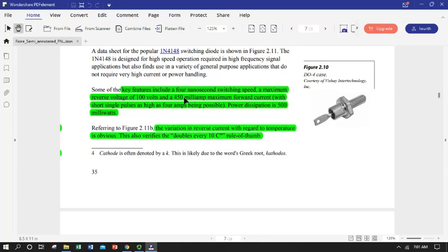You might destroy it or certainly alter its properties, and that way it won't work predictably in a circuit. So kind of rolling those two together, more of the forward bias, we're told that the diode won't dissipate more than 500 milliwatts. We can look a little in the future at how we calculate that when we pull in some circuit models, because to calculate power we need more than current, but we certainly know that our 450 milliamps is going to be a component of this. But this is how much power the diode can dissipate before it'll get too hot and stop working.